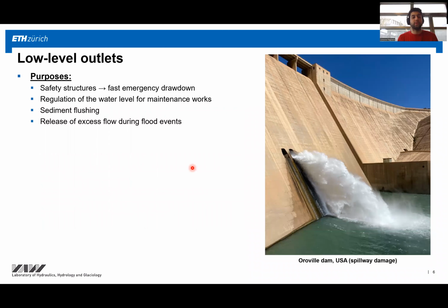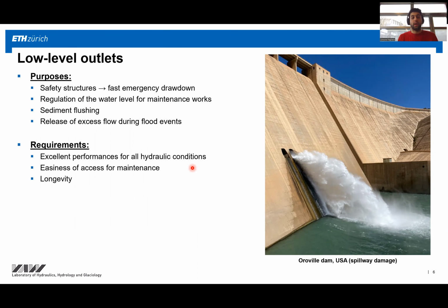Looking at low-level outlets, we said that they are safety structures. The main purpose is to have a fast drawdown of the reservoir in case of emergency or maintenance. But they are also used for sediment flushing and to release excess flow or environmental flow during flood events.